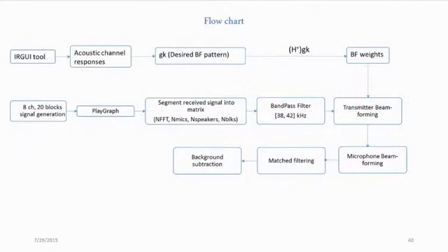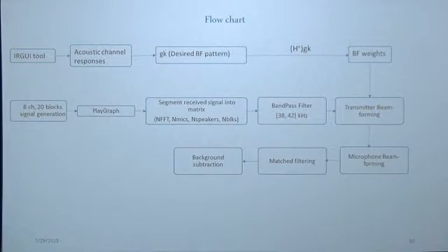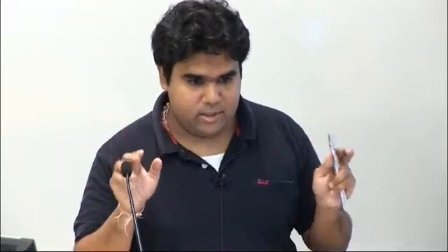that pattern, and then it's basically a multiplication of the pseudo inverse of the acoustic channel matrix, that is H, which is the acoustic channel response, and the desired pattern. So this gives us a curve fitting, and ultimately we arrive at the beamforming weights for this particular recording. If we do another recording for another measurement of the acoustic channel responses, we need to regenerate the weights.